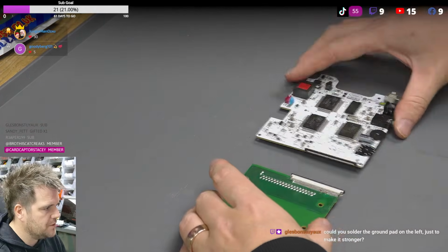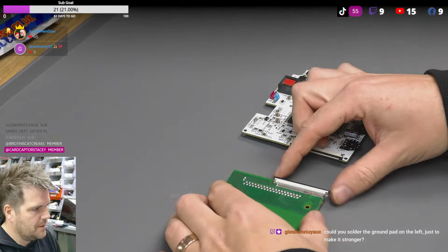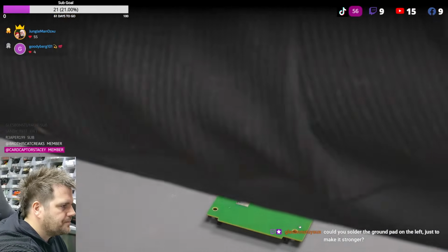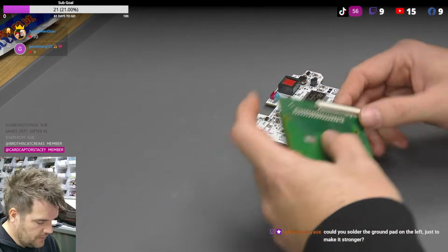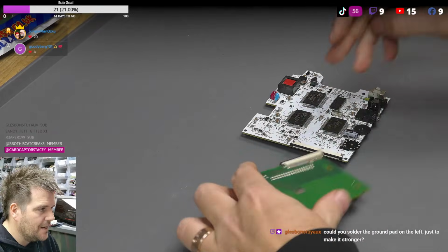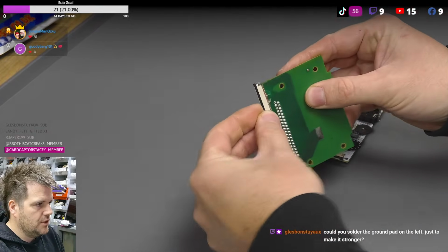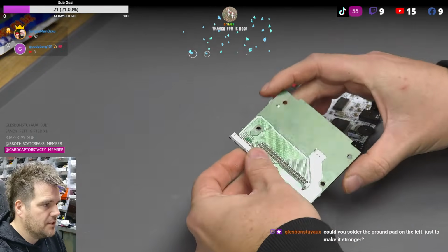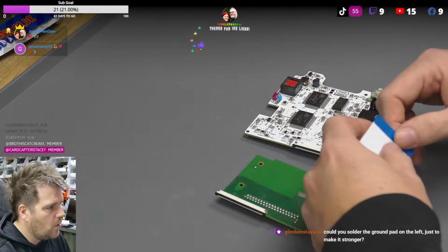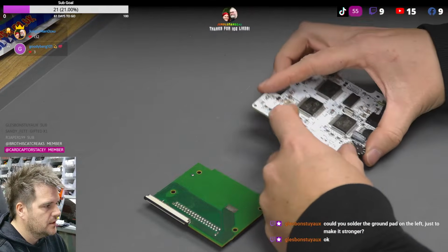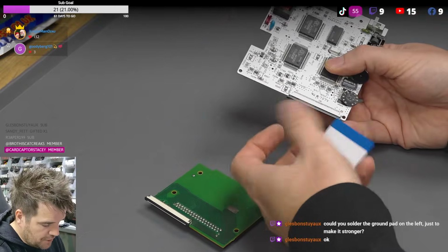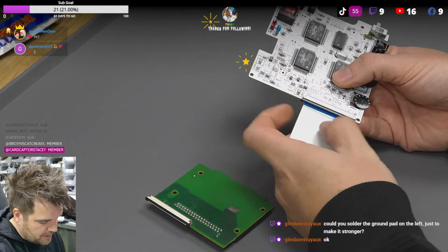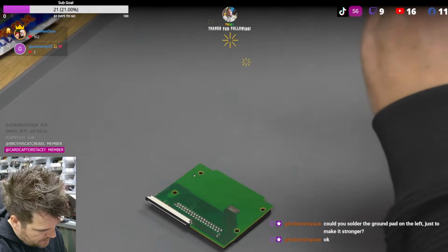That's rock solid as well because there's that many pins on this. They're rock solid. They don't even need fixing. Funny enough, as I was saying that, you said, can I solder the ground plane? I can, but honestly, this is rock solid. I'm trying to bend it. You literally can't even bend it off the board. Because it's such a wide pitch and large connector, you don't even need to in this instance, but you normally would. That was my concern with this originally, was fixing it in with no mounting points, but it actually holds itself in perfectly fine.